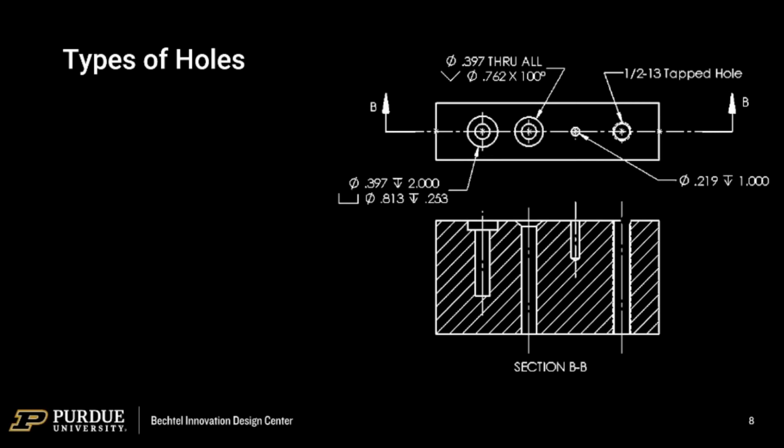The only really good engineering reason you'd need a flat-bottom hole is to say something like this plate needs to have a precision pin of a very specific length set in it, and the top of that pin needs to be a certain height above the plate. And then you would need a flat bottom hole because you have to clock that reference in Z very accurately. And you would probably call that out on a note so your machinist isn't tearing their hair out trying to get that whole flat bottom for you when they suspect that you don't need it. But if you tell a machinist, I absolutely need it this way, you'll get it. It's just that there's a price and time.